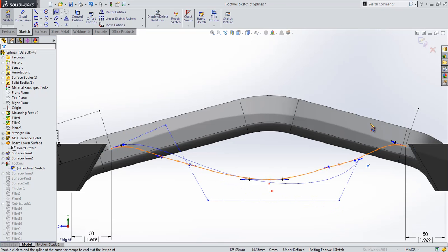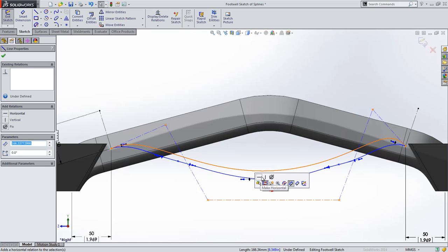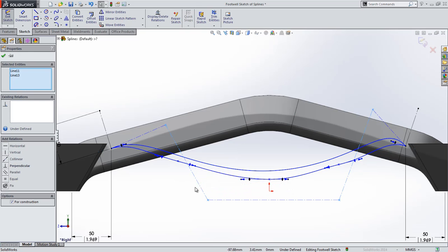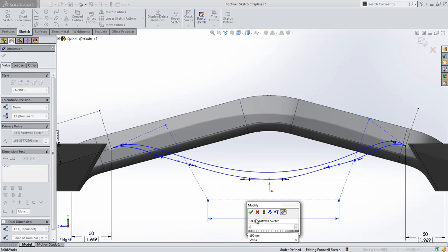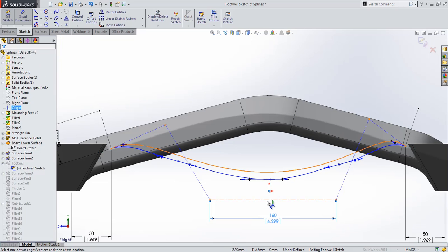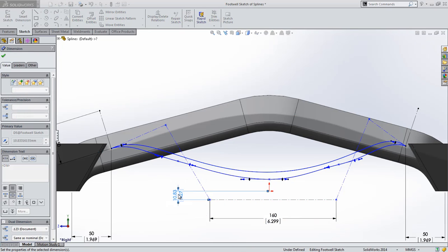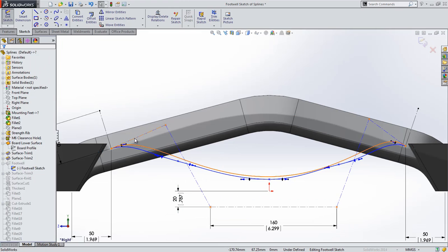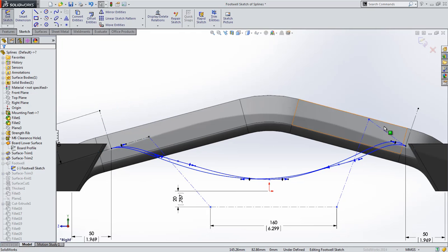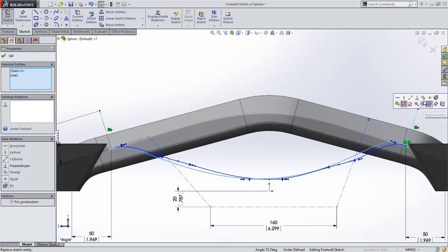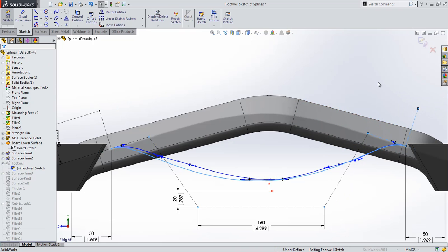Instead of individual spline points, which need to have the curvature and magnitude controlled, they're simply placed with construction lines. These lines can then be further defined using simple and familiar sketch relationships and dimensions all users are familiar with. As all the required relationships and dimensions are added, it becomes fully defined quite easily also, letting us know it will be fully controlled by any upstream design changes.